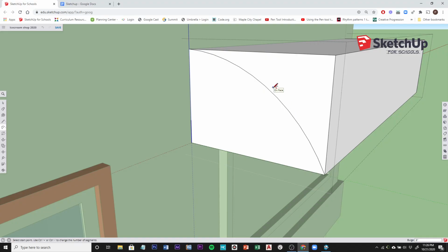So this is a little bit tricky. If you need to redo it, go ahead and click the undo button and try again. So I'll do that for you. I'll show you another example. So click in the upper left-hand corner, lower right-hand corner, and then up on face 6 inches, 6 quotation mark, enter.